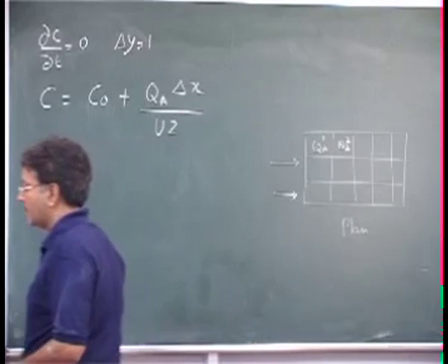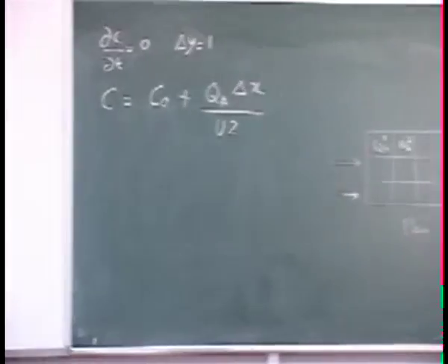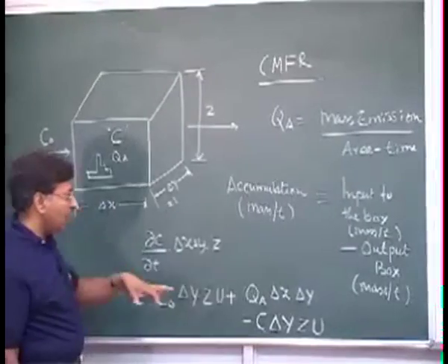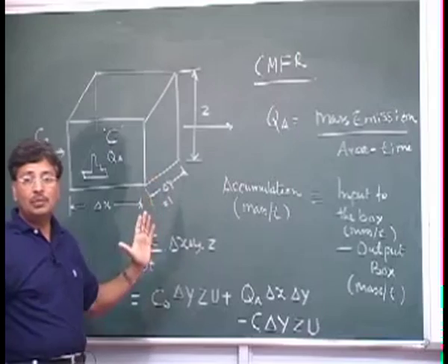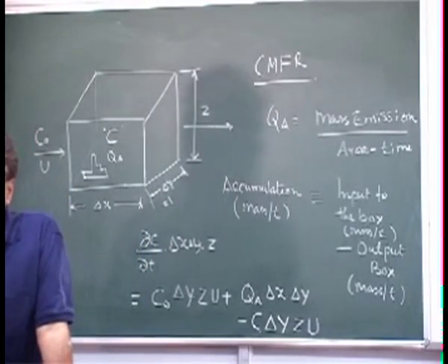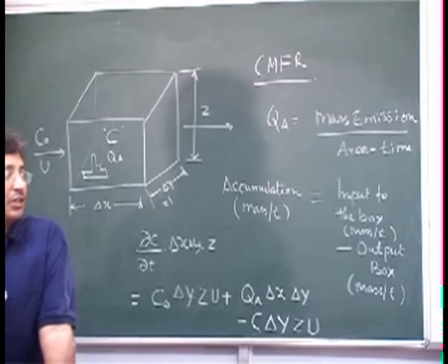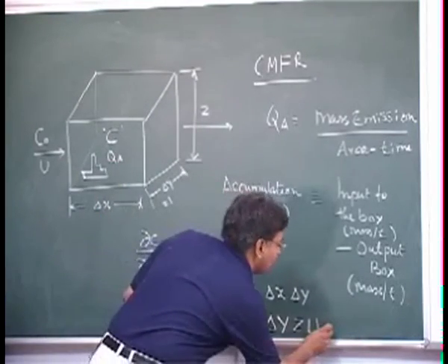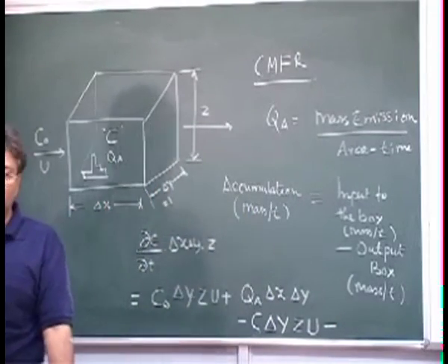Before we make some example and things like that, suppose the same pollutant was decaying in the box. Okay. It means the output is not only because of the wind that is cleaning the box, but there is a decay, and the rate constant for decay is, let's say, K. Okay. You have done that before. That is a decay rate constant for that pollutant, whatever that pollutant is. So it means concentration will decrease. Okay. What do I write if decay constant is K?